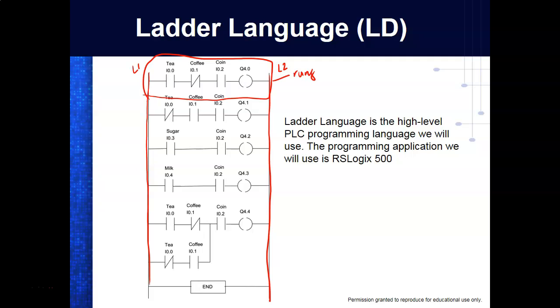So this is saying that we're coming through here, and it says get whatever's coming in on input. This is Siemens, by the way. Input slot 0, bit 0. This is normally closed. We'll look at this, or examine if open. These are actually coming from input devices.